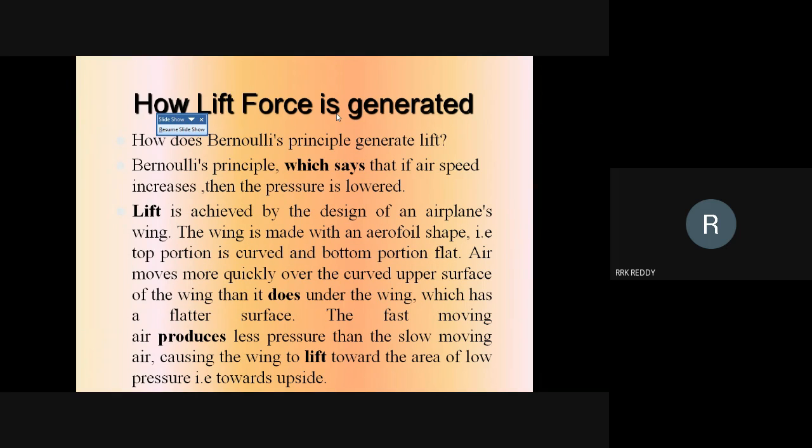Obviously the fast-moving air produces low pressure on the top portion and high pressure on the bottom portion. Due to this pressure difference, the aircraft tries to move from the high pressure to the low pressure side, that means in the upward direction. In that way the lift force is generated. So the aircraft gets lift based on Bernoulli's principle.